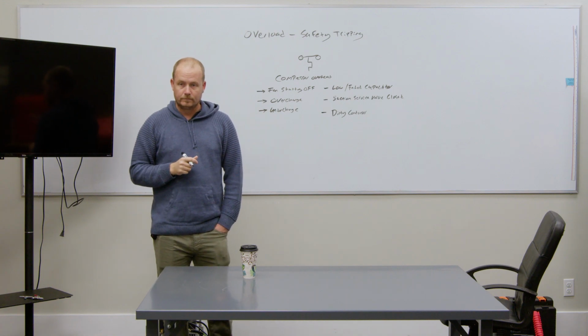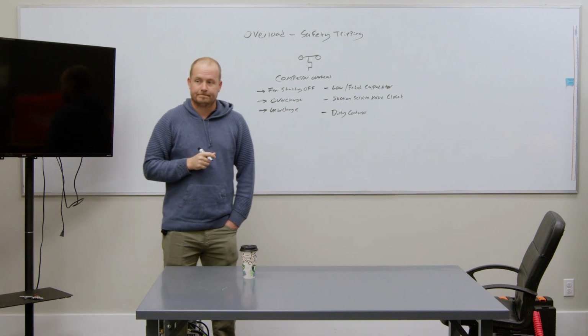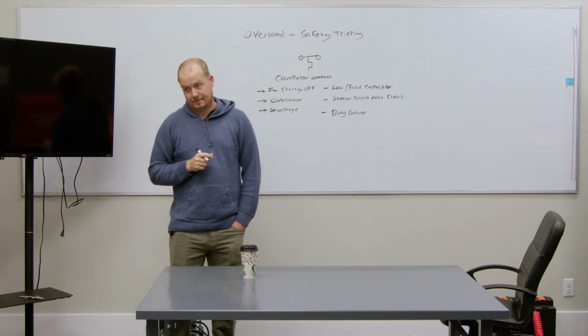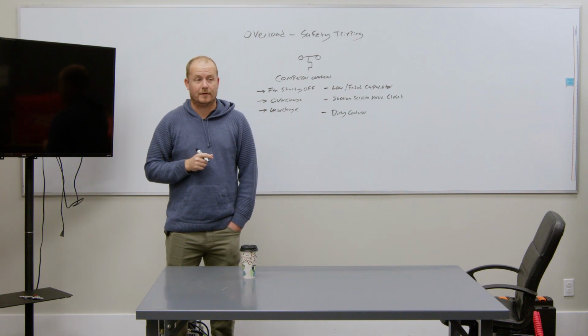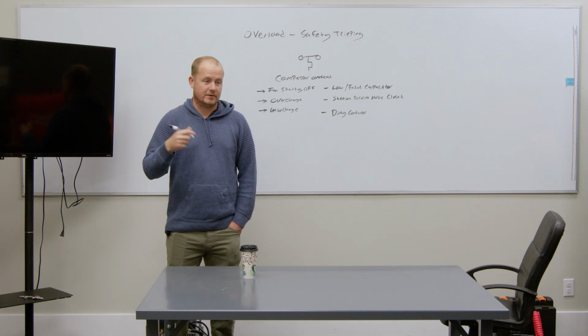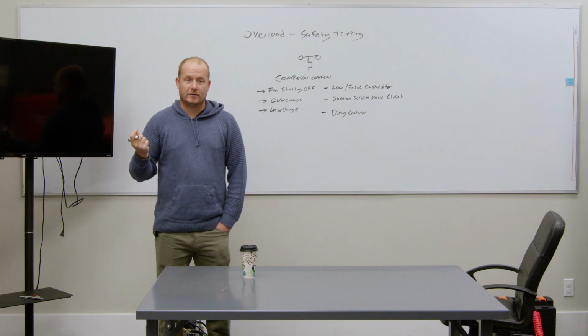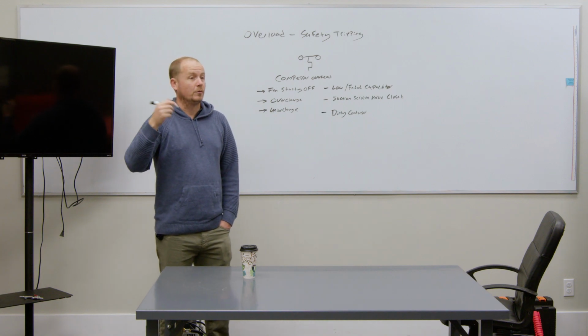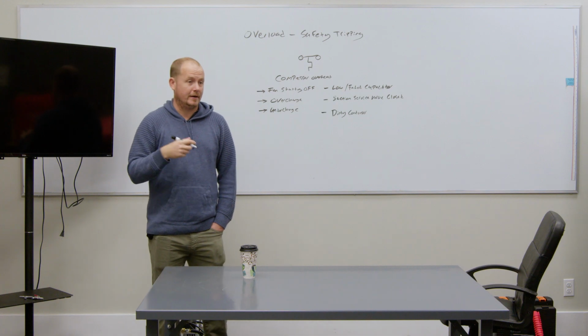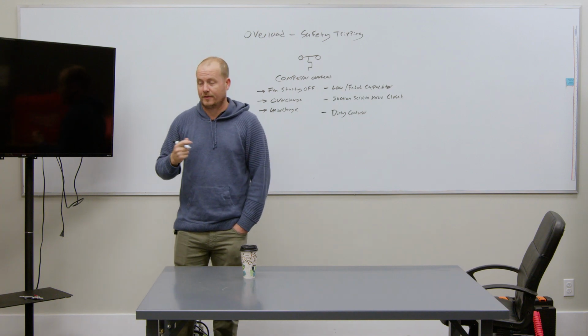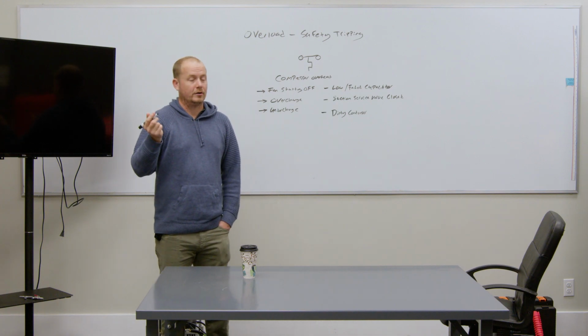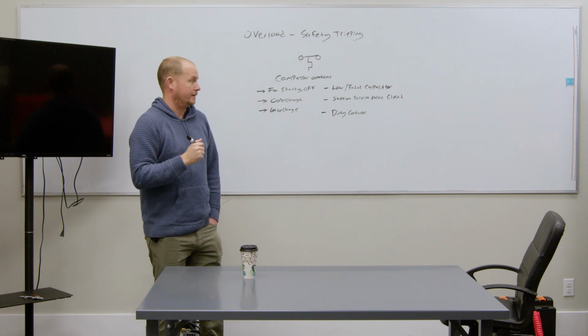You replace the capacitor, fan comes on, the compressor does not. Yes, that's also a common one. Your capacitor is failed, your fan wasn't running, your compressor was running, especially when you have a separate fan and compressor capacitor rather than a dual, and your compressor's still overheated. Now you've got to cool that down.